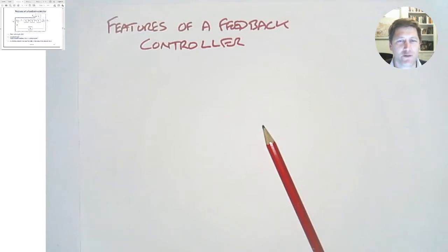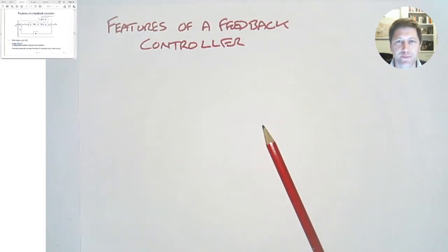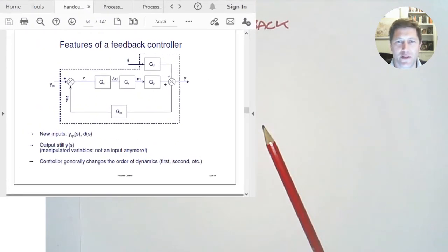The previous lecture saw us follow a loop around and all of the transfer functions that are required to represent the measurement, the actuators, the control system, disturbances, and so on. So this is where we got to last time. We can see our control system and we can see how the signal comes around, and then the comparator creates the error signal. The error tells us that something needs to be done because we're not at our set point. That could either be due to a disturbance or it could be due to a change in the set point. And then we've got the mechanism now with the choice of controller, choice of control parameters to make the difference.